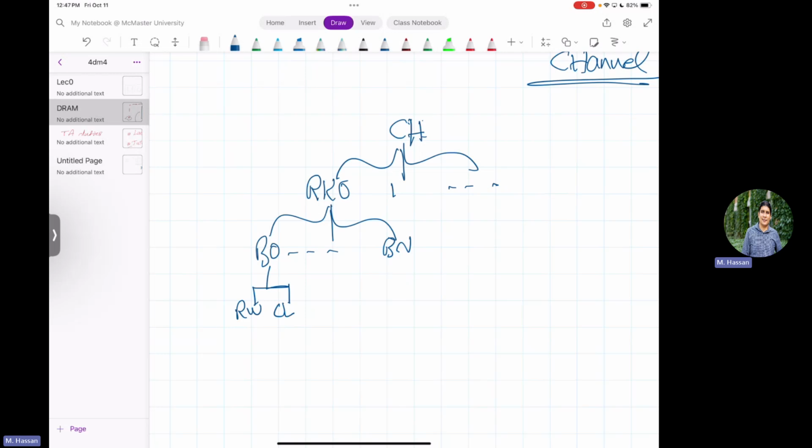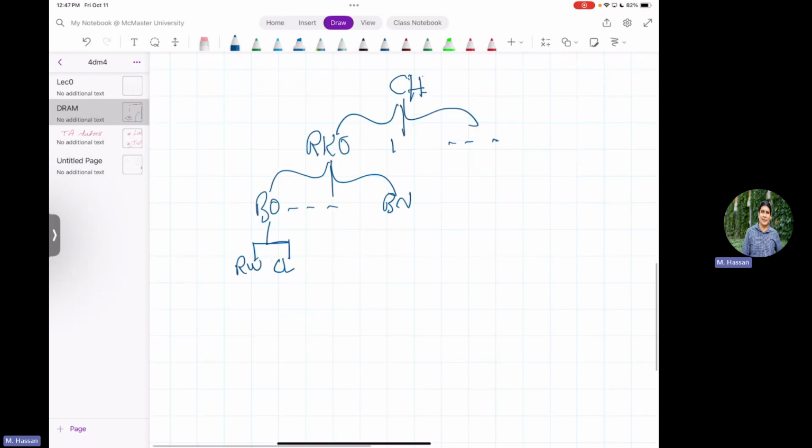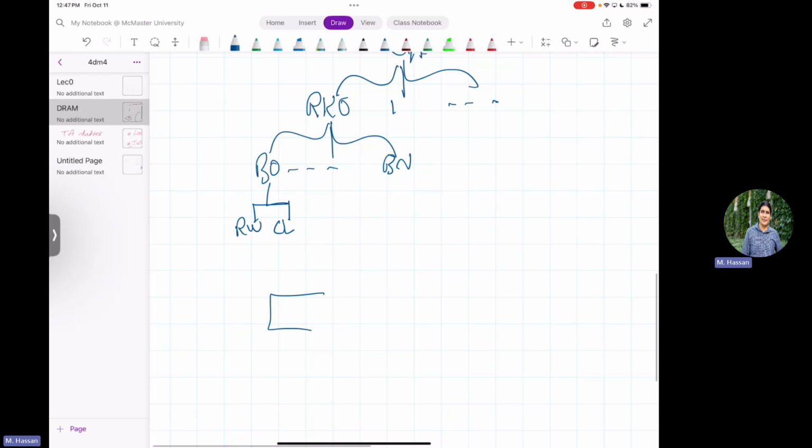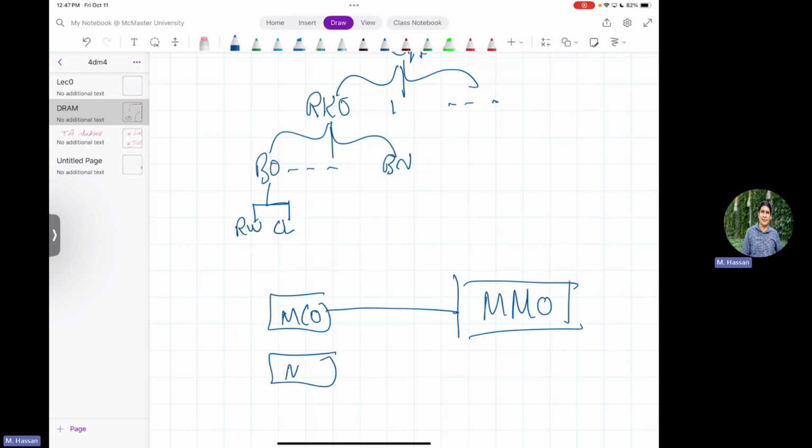As long as you have a separate memory controller for every channel, that's a different channel. This is our definition of a DRAM channel. A DRAM channel is one memory controller on a chip connected to, for example, main memory 0. Then you have another memory controller that connects to main memory 1, and so on. By doing this, they are completely independent. Independent means on the same cycle, you can serve requests at channel 0 and serve requests at channel 1.